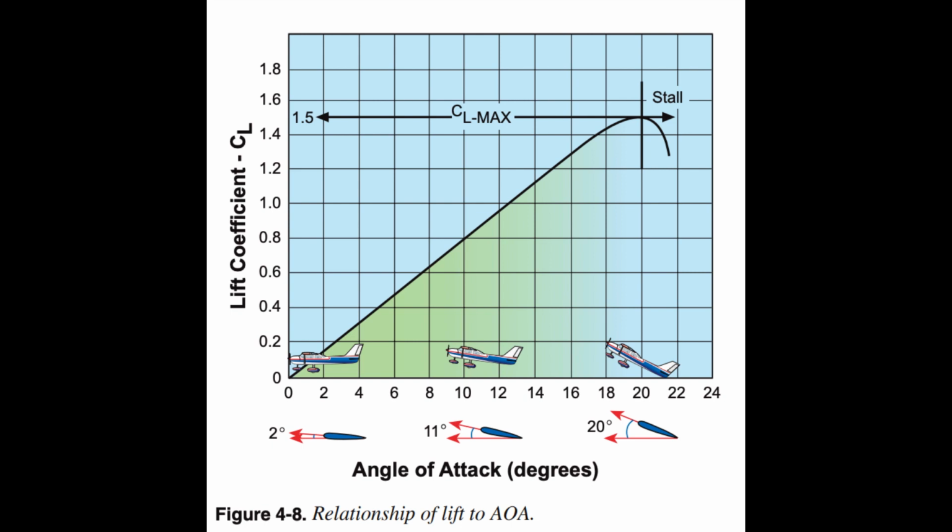The most precise method of controlling flight path is to use pitch control while simultaneously using power, thrust, to control airspeed. In order to maintain a constant lift, a change in pitch requires a change in power, and vice versa. If the pilot wants the aircraft to accelerate while maintaining altitude, thrust must be increased to overcome drag. As the aircraft speeds up, lift is increased. To prevent gaining altitude, the pitch angle must be lowered to reduce the AOA and maintain altitude.